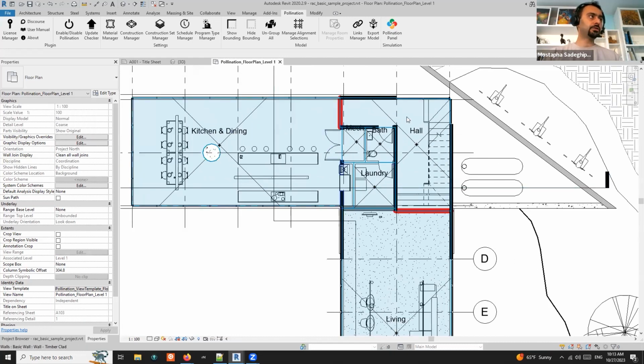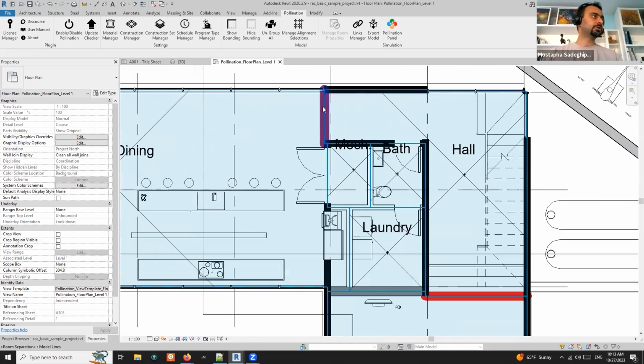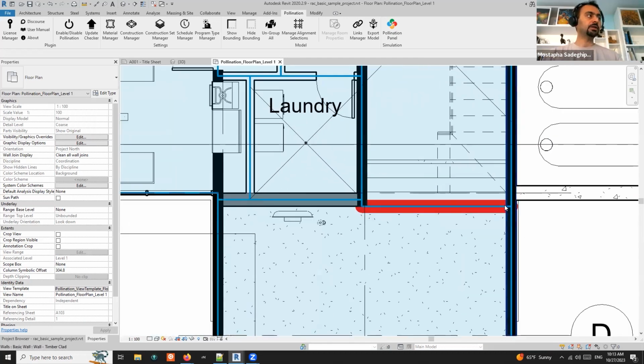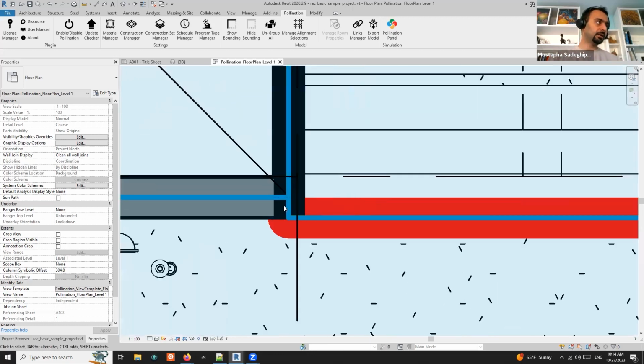So what are the most important things? One is to make sure all the rooms are placed, because we're going to use rooms, right? If it's spaces, you make sure all the spaces are placed, or all the areas are placed. The other one is you want to make sure you see all these what's called separation lines, and you'll see how these separation lines can be a problem. People draw separation lines in Revit like a sketch most of the time, from what I've seen.